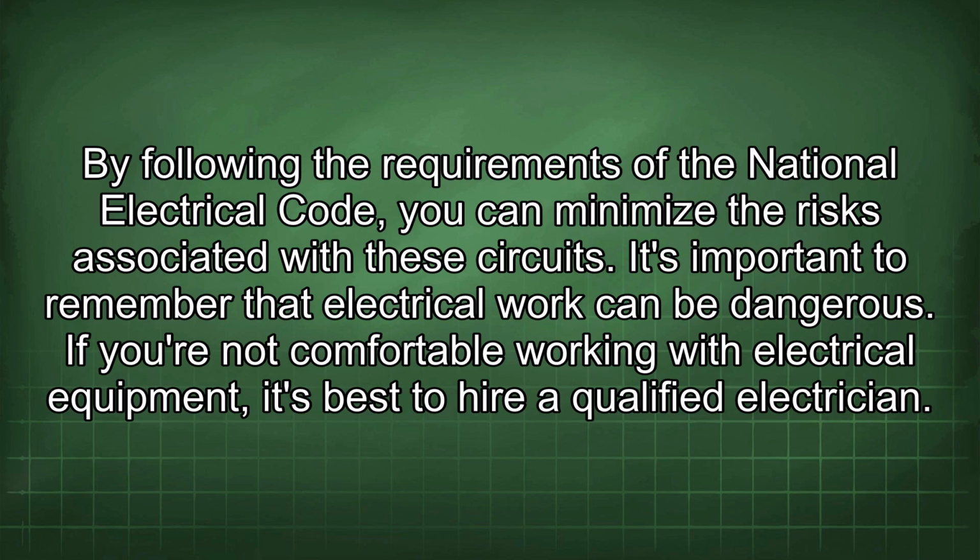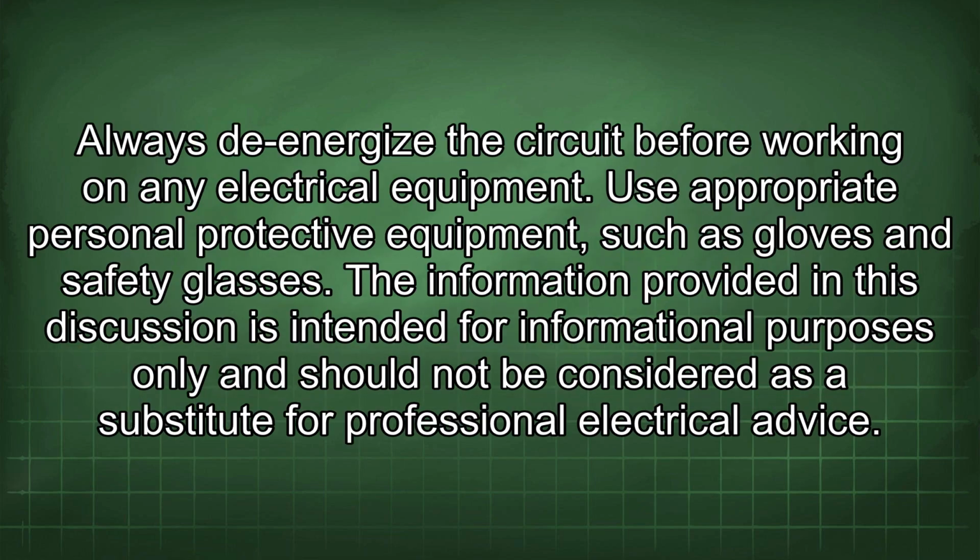It's important to remember that electrical work can be dangerous. If you're not comfortable working with electrical equipment, it's best to hire a qualified electrician. Always de-energize the circuit before working on any electrical equipment. Use appropriate personal protective equipment, such as gloves and safety glasses.